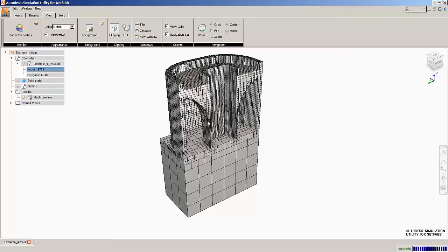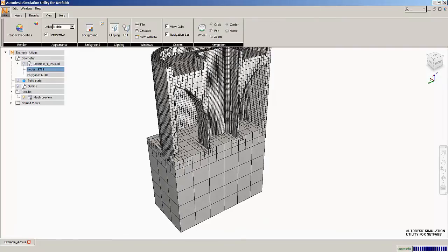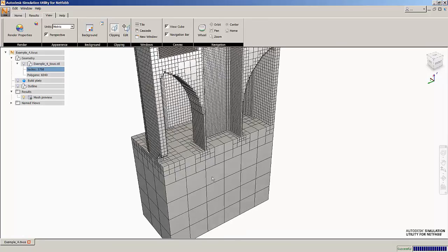And another thing to notice with the mesh is that it can handle, this is unique to this solver, it can handle hanging nodes, they're called. So a node like this node that doesn't share a node with a neighboring element. And that becomes a constrained node. And this allows us to coarsen the mesh very aggressively away from where we have fine geometric features.